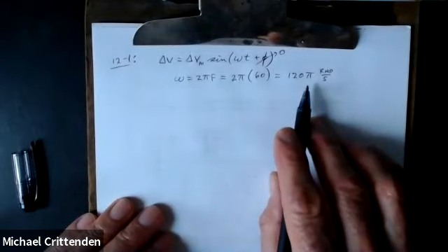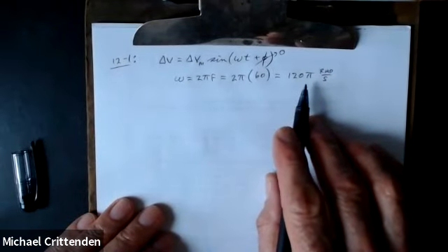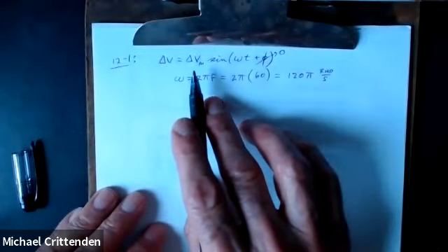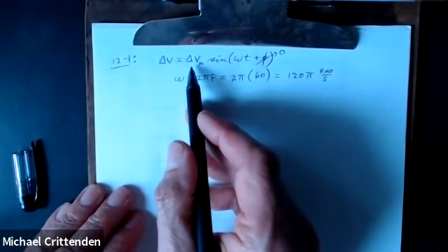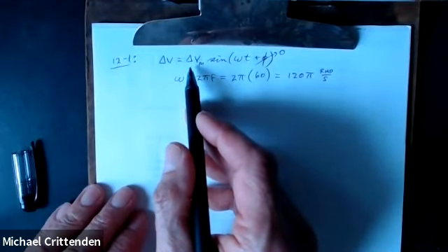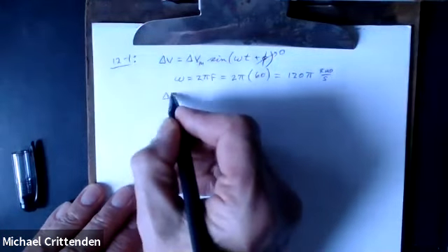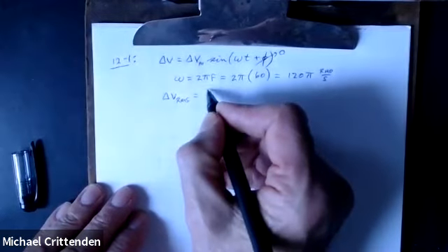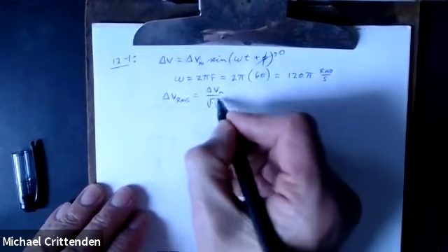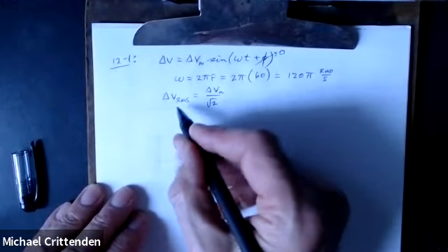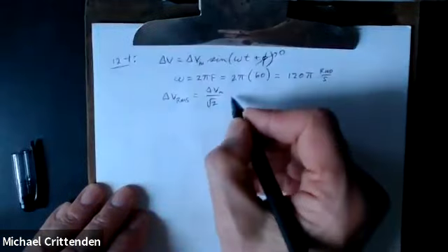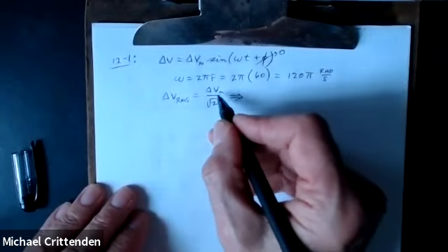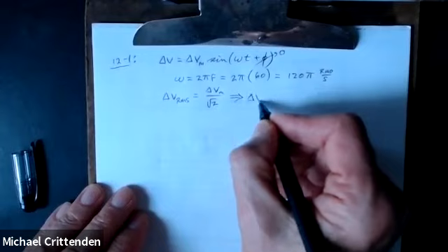If you don't want to be quite so exact, that 120 times pi is around 377. As for the amplitude, no, don't put the 120 volts in there. What have I said that like 5 or 10 times in the last few minutes? Maximum divided by the square root of 2 is RMS, is the way it says it in the note packet, and I think I probably wrote it the same way on the formula sheet. Well, since the maximum is what we're after, got to rearrange it.